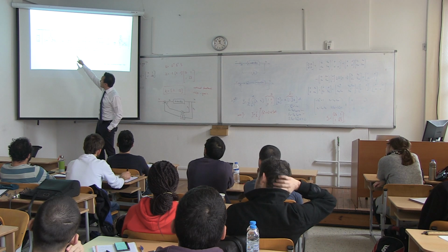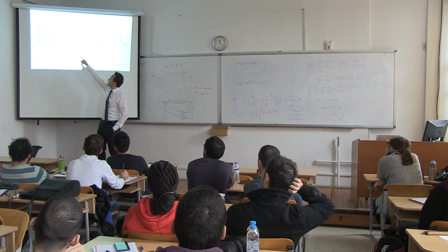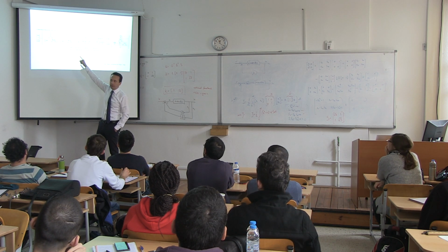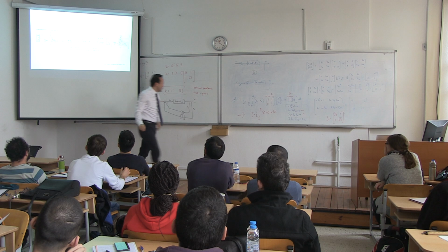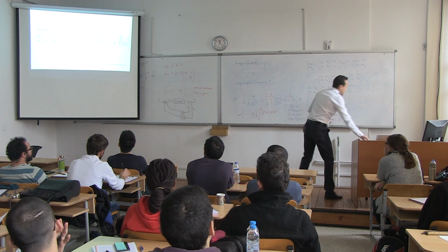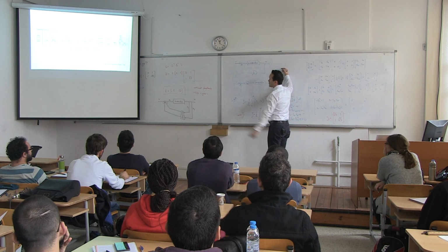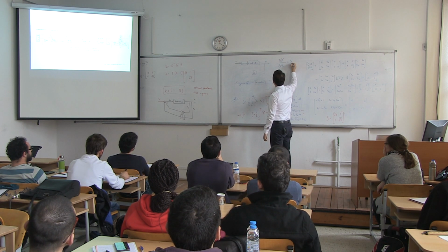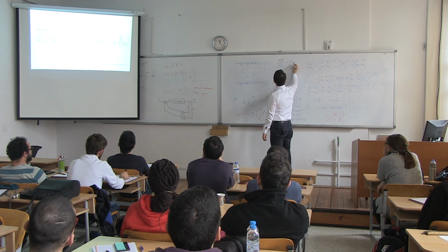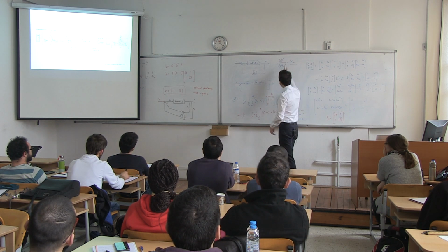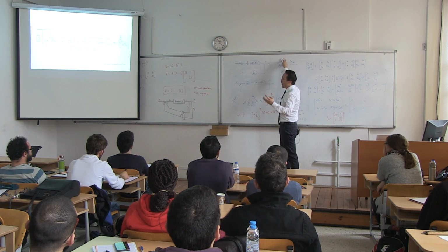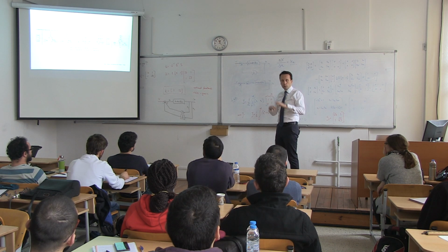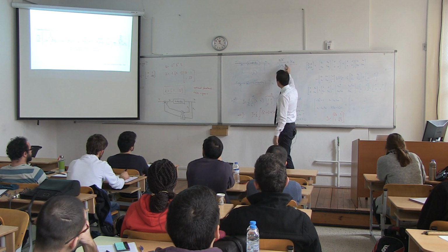You see that you have the aerodynamic derivatives, del x del u divided by m. You see the first element over there? Del x del u divided by m. So in order to calculate the first number on the A matrix, which is a 4 by 4, you need to calculate del x, del u, and you need to know m. Okay? So this is an aerodynamic derivative. Basically, it says how much does the force change if you change u on the aircraft, if you keep everything else constant. So how do you calculate that?